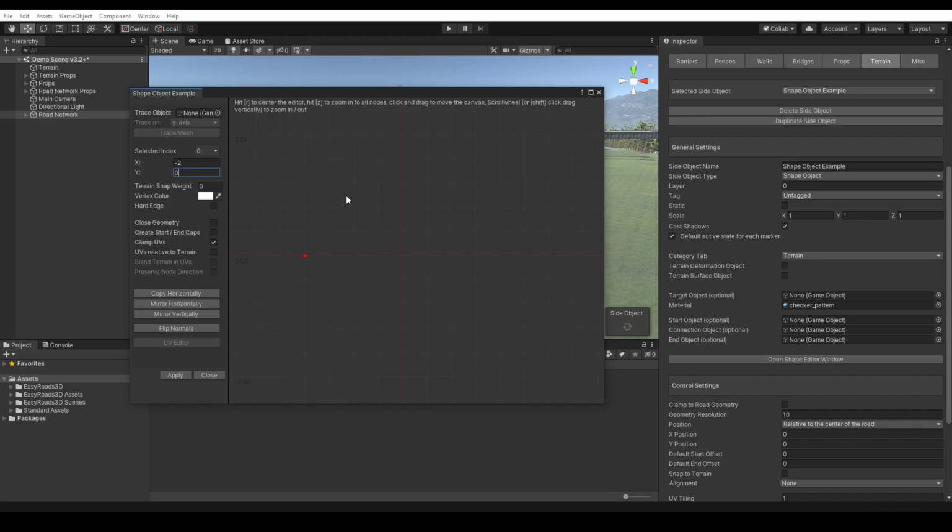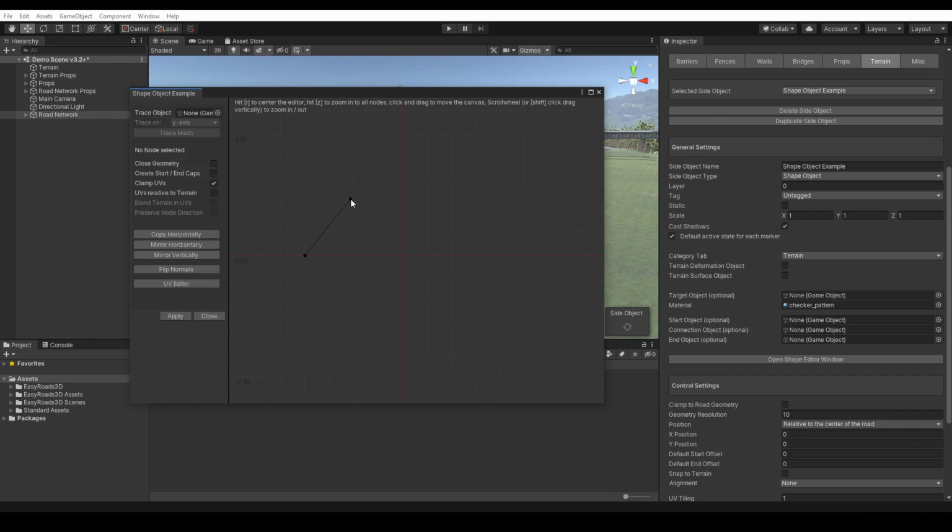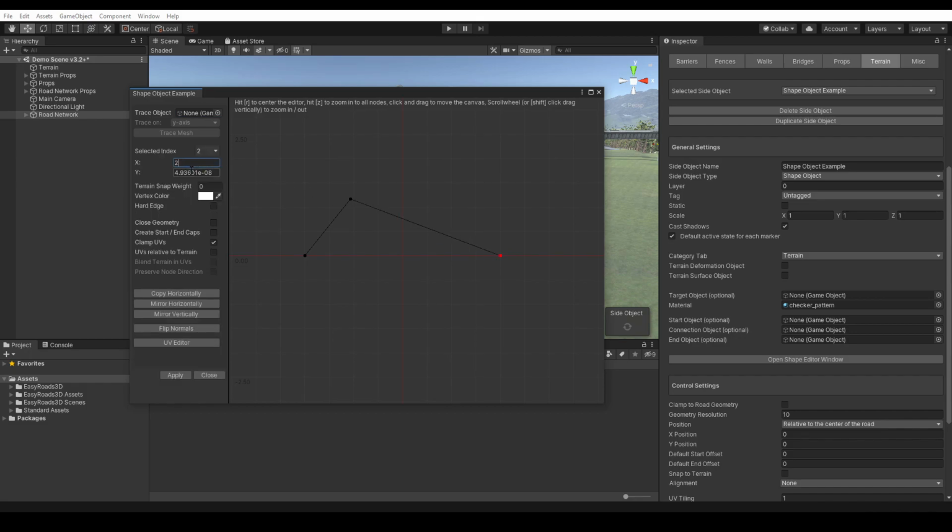Also note that in order to create a shape with the normals pointing upwards, we add nodes from left to right. When that is not the case, the normals will point downwards. This is something to check when the shape is not visible in the scene. In that case, we can easily solve this here with the Flip Normals option, which will reverse the node order.